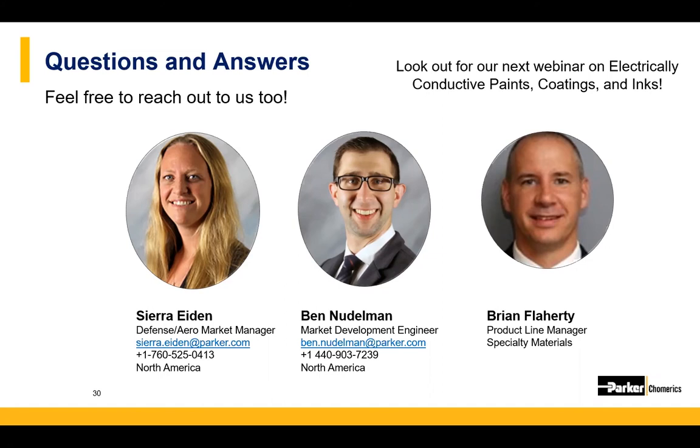Yeah, so that's a good question. That is something that Chomerics has the ability to characterize in-house. We put a lot of our materials through thermal cycle testing, and we test shielding before and after various thermal cycles. It usually has a lot to do with the type of material and also the substrates, how closely the coefficient of thermal expansion matches between the substrate that you're applying the compound to and the compound itself. That has a lot to do with how it will perform after thermal cycling.